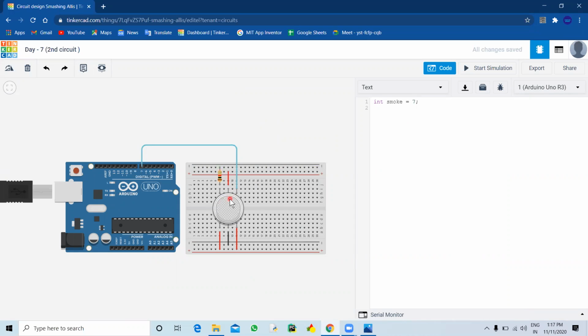And as I told you that it is interchangeable, if you just select this and from this button, you just shift this like this. Okay, wait. First, the wires: I will not connect them directly with the pins. I will connect them with the pins of the breadboard. So if I shift it, then no effect comes. Okay, so now if I just shift the gas sensor, now you can see B1 has come here and A1 has come here. B2 is here and now A2 is here. So now it is interchanged. I have just reversed it. Now also it will work absolutely fine and we don't need to make any change in the code.